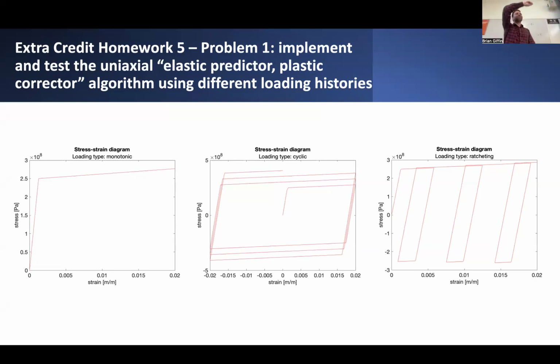As you go through multiple cycles, the diameter or bounds of these plastic hysteresis loops become bigger, and that is characteristic of isotropic hardening behavior. In contrast, if we had no increase in those bounds, but still had some kind of slope associated with these diagrams, that would be more characteristic of kinematic hardening behavior.